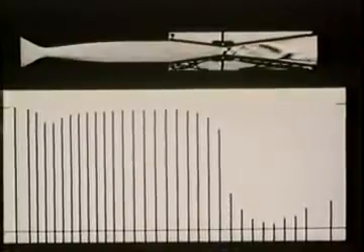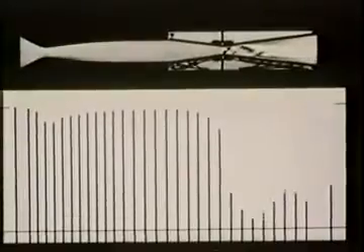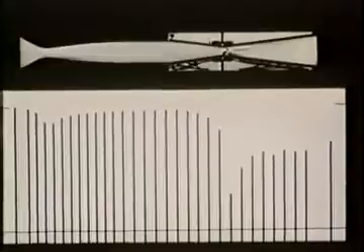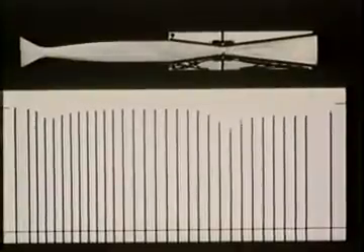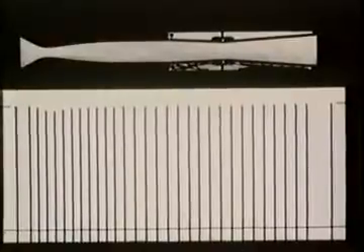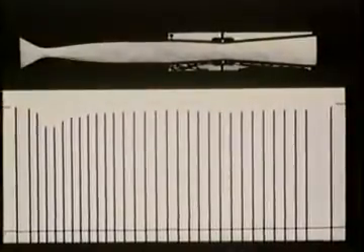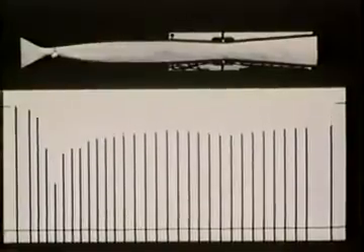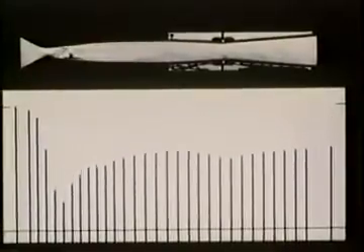Now let's make the second throat slightly larger than the first. As we open the valve, the first throat chokes, and a shock wave appears in the nozzle. Then the second throat chokes, and we can no longer affect the first shock wave, only the second one.